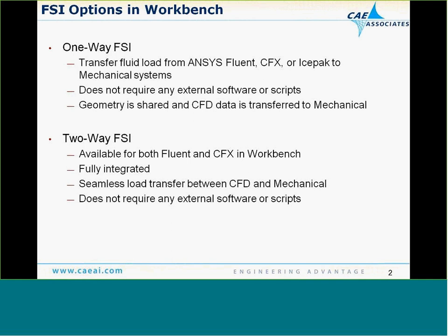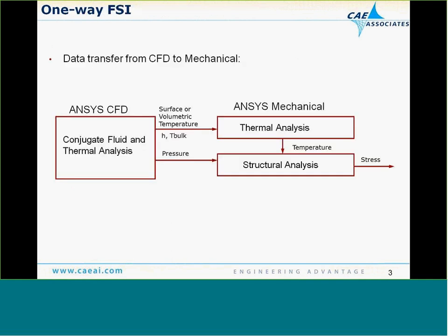Why are we interested in doing this? Because in many situations, we do not require a two-way FSI coupling. It's rather complex, and it requires a lot of CPU time to get the fully coupled two-way FSI analysis done. And it requires data transfer at every time step until they converge, both on the CFD side as well as on the Mechanical side.